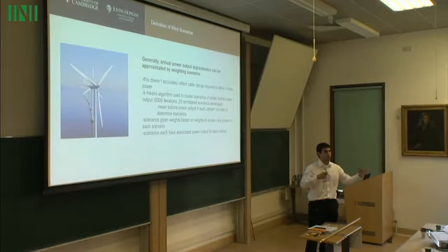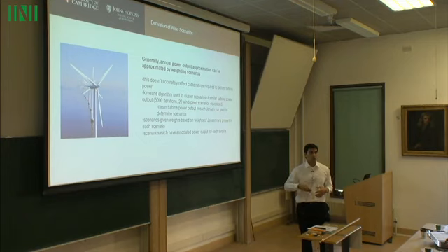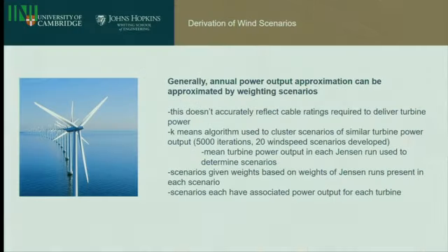So if you don't break your optimization process into different energy production scenarios, you won't be accounting for the true production possibilities of your curve. So we used the k-means algorithm to find these clustered subsets of energy production scenarios so that our model had a good representation of what the actual energy production was.